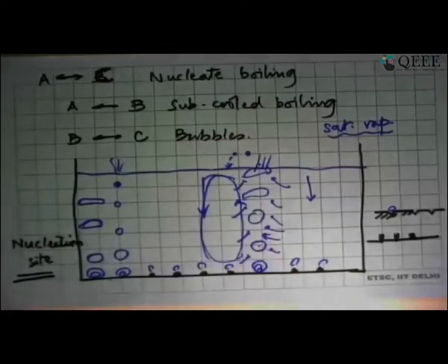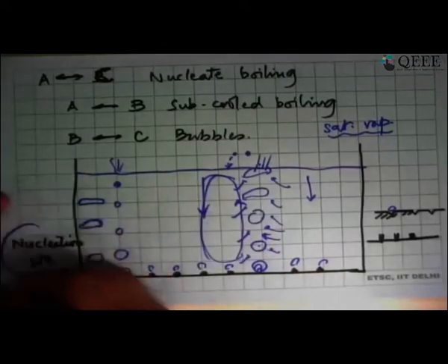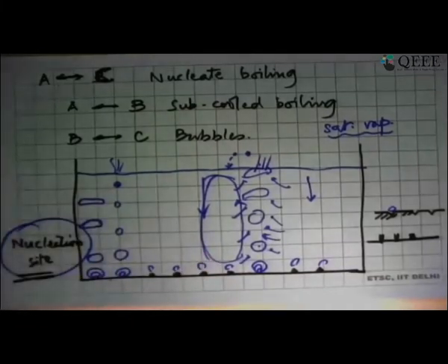So what we are seeing in this whole process of nucleate boiling is a very important thing: how to get this nucleation coming in, how do I control it, or can I predict it? It is the same issue that comes up in boiling water reactors, where if you have boiling taking place on the outside of a tube, the bubbles will form where there is a nucleation site, and gradually that is the site which will get eroded, and you will see another reason why that will happen. And that is where the fuel rod of a nuclear reactor could weaken, and you would like to know it as quickly as possible and probably take it out of action before it fails. So nucleation and surface finish are very important things connected to nucleate boiling.